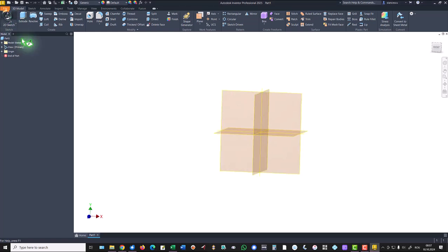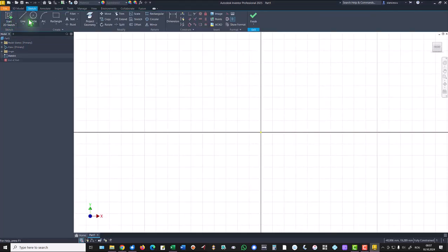Let's create a new sketch in this plane. We draw two lines, 1, 2. Now I want to continue with the line perpendicular on this one. To do this, I hover here and I find the perpendicular. Then I want to create a parallel to this. I hover on the line or I go over it and I go right here.